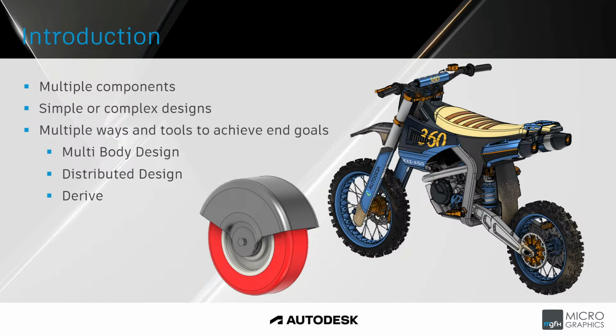And it does this in a couple of different ways. Fusion 360 allows you to achieve this end goal of creating an assembly in sort of 2 main fashions or 2 main ways. The first is multi-body design, and we'll go on to the next couple of slides which cover what multi-body design is. But in a nutshell, it allows you to have one design file and have all of your components designed within that single design file.